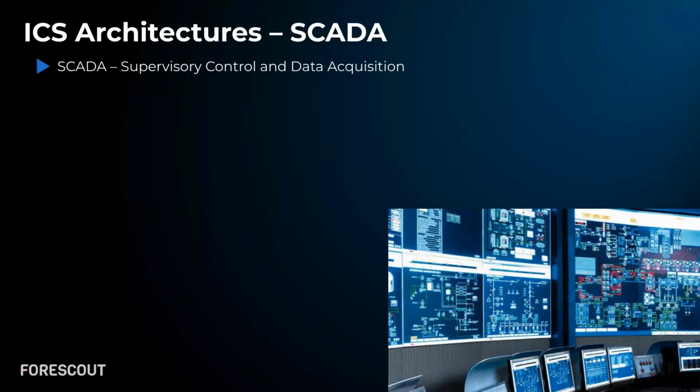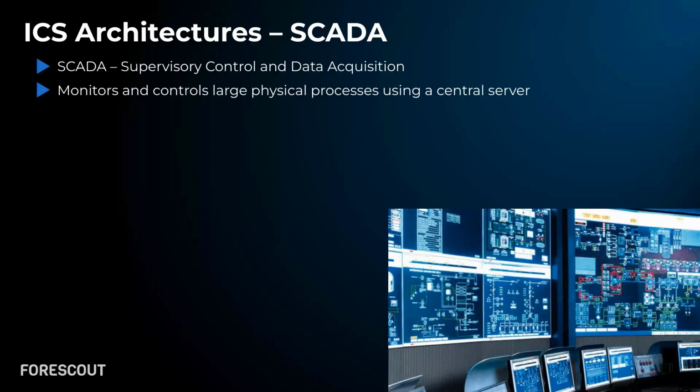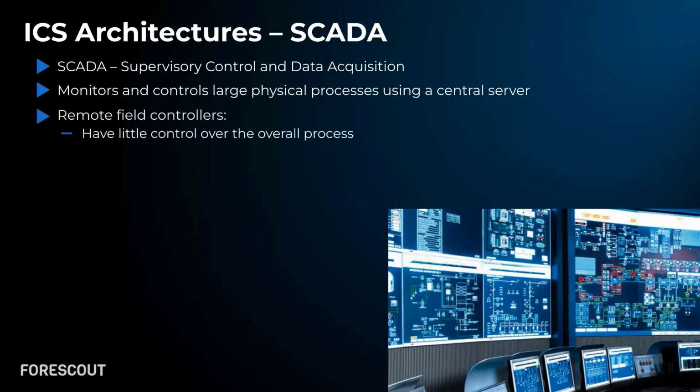The first ICS architecture we will discuss is SCADA, which stands for Supervisory Control and Data Acquisition. SCADA is an architecture that monitors and controls a large physical process using a central server, the SCADA server. Usually, SCADA architectures rely on centralized controllers, which make decisions to adjust the various processes based on data collected from these controllers. The remote field controllers have less control over the process, and their main function is to acquire and pass along the data that is used to make decisions.